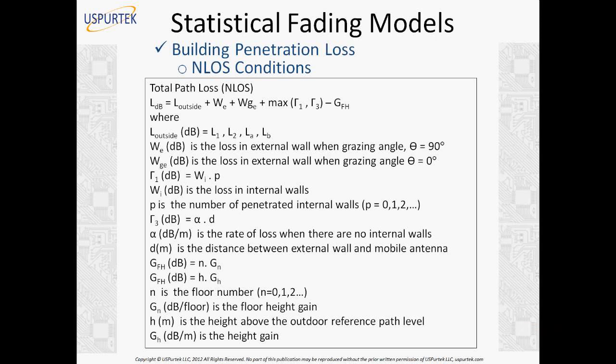So this is from the layout of your cell actually. You have to get a layout of the place where you have to see what is the building layout, or what is the plan of the area over there, and where is the cell tower. And you can just from simple geometry draw how the signal will reach the external wall of the building, and just estimate an angle over there. If you don't have access to this type of plan, then just assume 90 degrees. That's it. Just assume 90 degrees, that the cell tower is transmitting a signal at 90 degrees to the external wall.